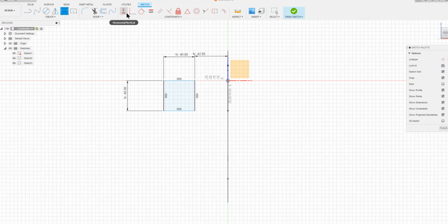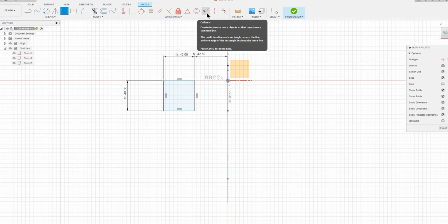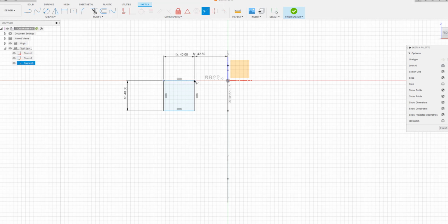Then with that done, I want to make sure that these things are anchored to the coordinate line. So I'm going to do here a collinearity. I want a collinearity between this, and this. So I want everything there to be on this. So that anchors this to the origin there, to the coordinate line.